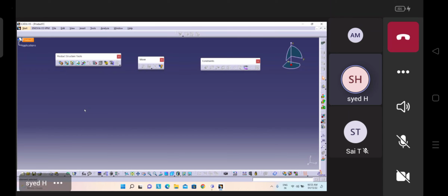What we will do? First of all, we will create that nib separately by doing the assembly. Then that nib assembly we will call in the refill assembly. In the refill assembly, we have the refill, ink, and that nib. Those three things we will call and make a small assembly. And that again we will call under the big assembly, that is my complete pen, like the cap, the upper part of the pen, and the lower part of the pen. If it is a pen that we press with the back side, then we have a spring and the cap, all those things are there.